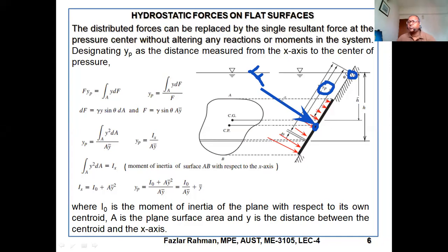You see, this resultant force actually is coming from the fluid. But as an engineer, how will you protect it? That means you have to consider that this will be my reaction force from the support. If this is a reaction force, then in the support, its force will be along this direction, right? You can think some force going to the top support and also the bottom support. Now, if this body is not rotating, then the moment due to the force F and the moment due to all the force working in the small area has to be equal.